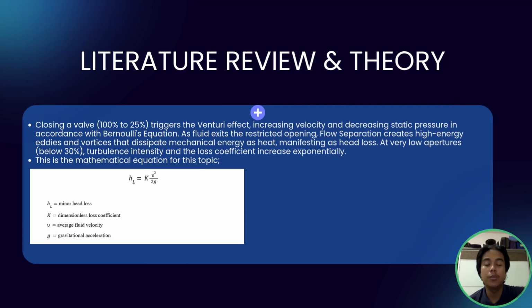Now I will be presenting the literature review and theory. Closing a valve from 100% to 25% triggers the Venturi effect, increasing velocity and decreasing static pressure in accordance with Bernoulli's equation. As fluid exits the restricted opening, flow separation creates high energy eddies and vortices that dissipate mechanical energy as heat, manifesting as head loss.